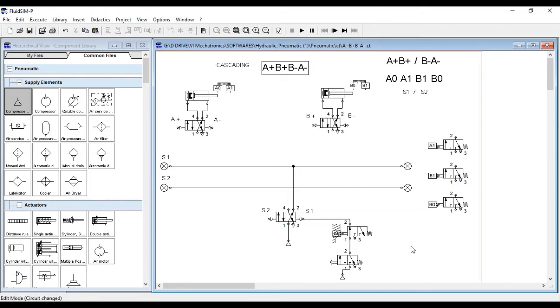That means now when I push the button, this power source is connected to S1 and this S1 line is powered up. Now I want A plus to be connected. So A0 is now connected, now S1, and because of S1 A plus will occur. Means the sequence is A0, because of A0 S1 will occur.